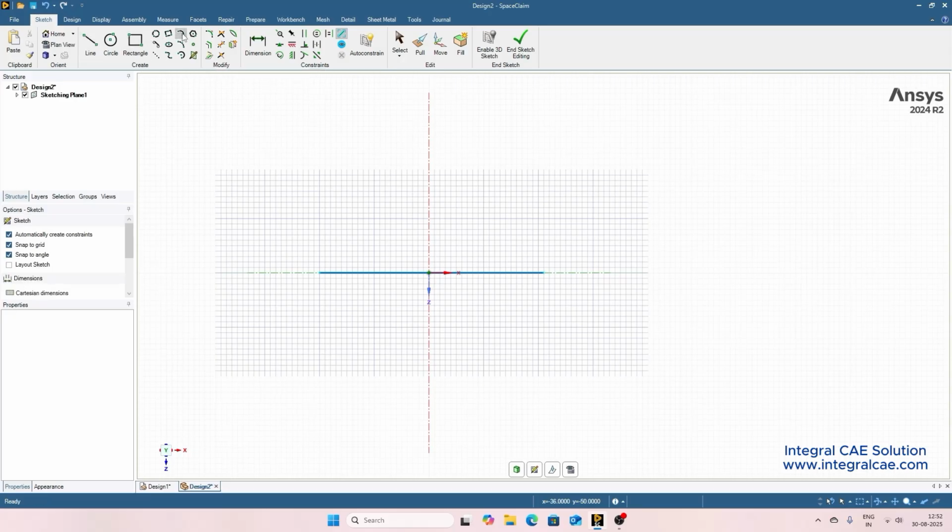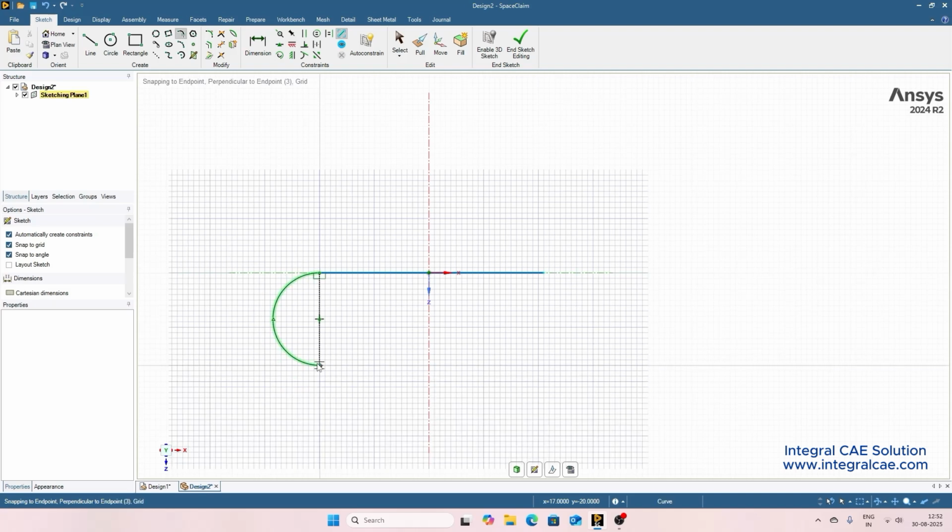Let's click this option. First point to select is the point from where you want to start the arc. Hence, select a location on the line and then move the cursor. This will start the arc. We can set the diameter and sector angle as well. You will notice that a perpendicular line started from the selected point or tangent location. This line forms the radius and it maintains the perpendicularity while we move the cursor. Once we click again, it will end the curve and this will form a tangent arc to this line.